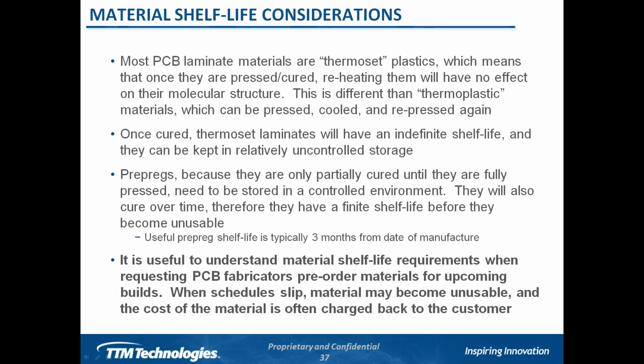This is different than thermoplastic materials, which can be pressed, cooled, and repressed again. Because we deal with thermoset materials, I always tell customers you get one shot to press it right, and if something happens and the press breaks down, or you get a power failure, then you basically have to throw away that press load and restart it.